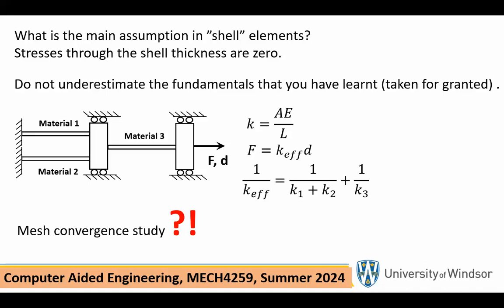If they are too far apart in your judgment, neither one of them is acceptable. Just throw away the linear one, keep the quadratic or parabolic one, and now start making the mesh smaller and smaller and smaller in critical areas. That's the magic word: in critical areas. And then compare the results.